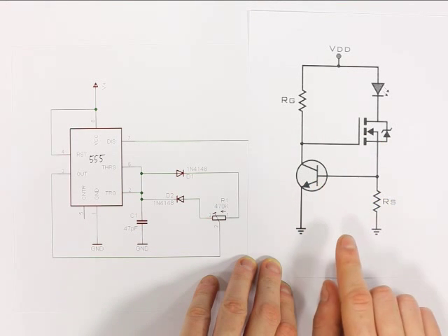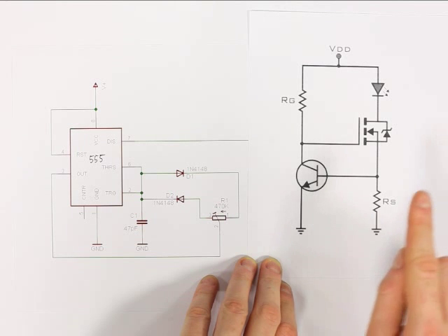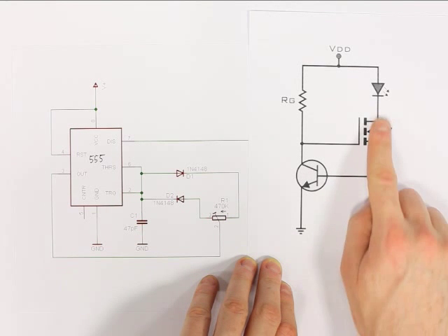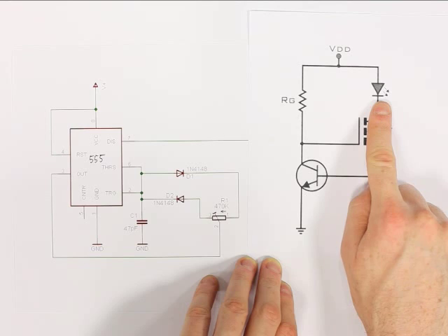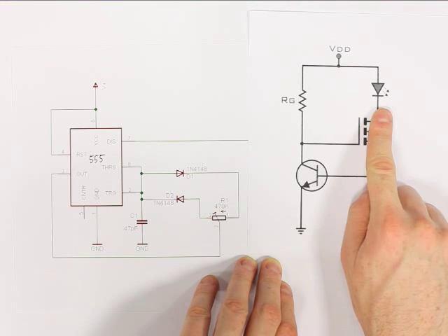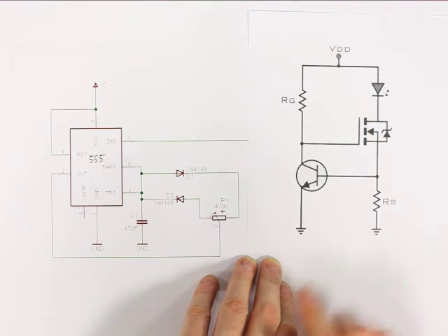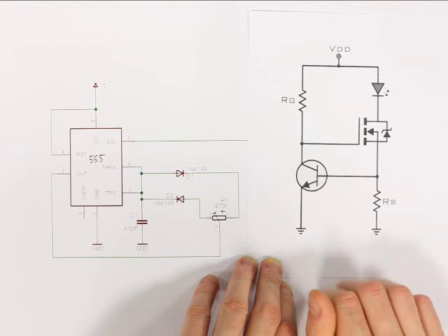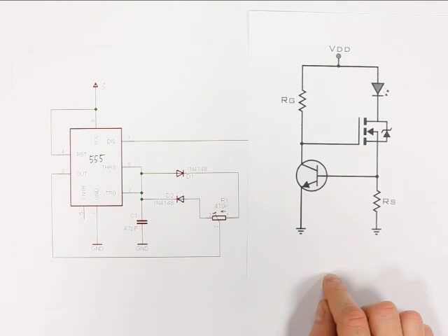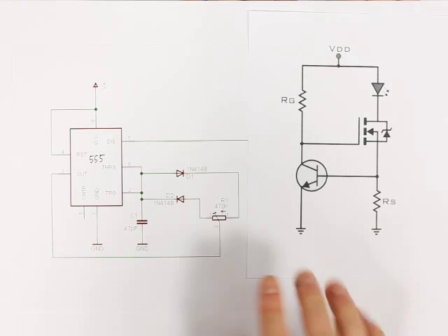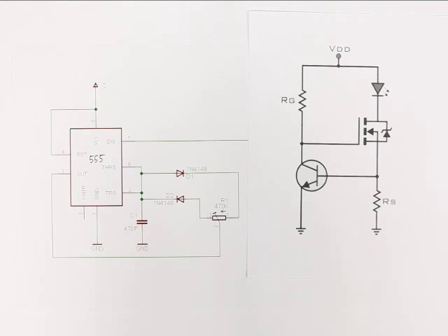So what we get is, at a 10% duty cycle, we'll have our LED outputting an apparent continuous light at 10% of its maximum output, and the whole circuit will be consuming just a touch over 10% of our normal power. So let's go ahead and implement that and see what it looks like.